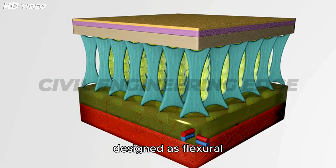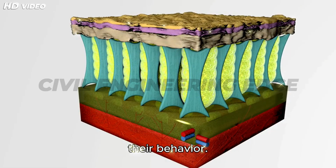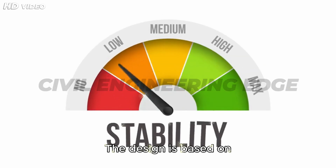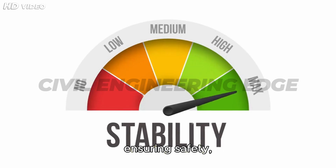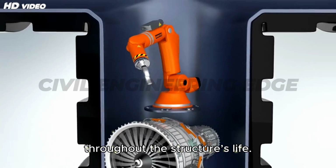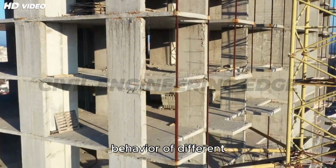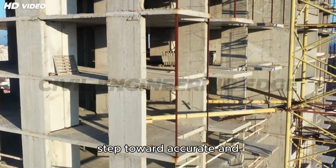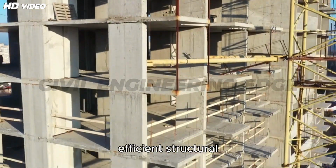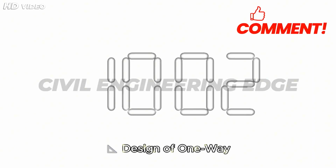Slabs are usually designed as flexural members, assuming the bending action governs their behavior. The design is based on the limit state method, ensuring safety, durability, and serviceability throughout the structure's life. Understanding the classification and behavior of different slab types is the first step toward accurate and efficient structural design, especially for real-world applications.